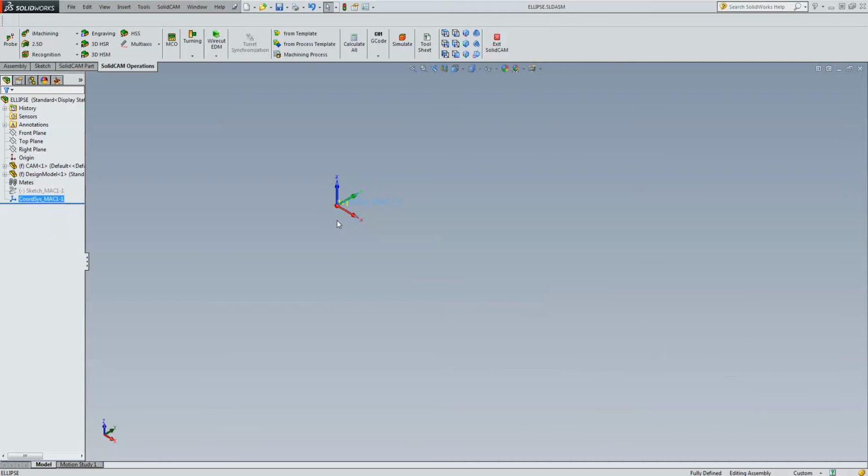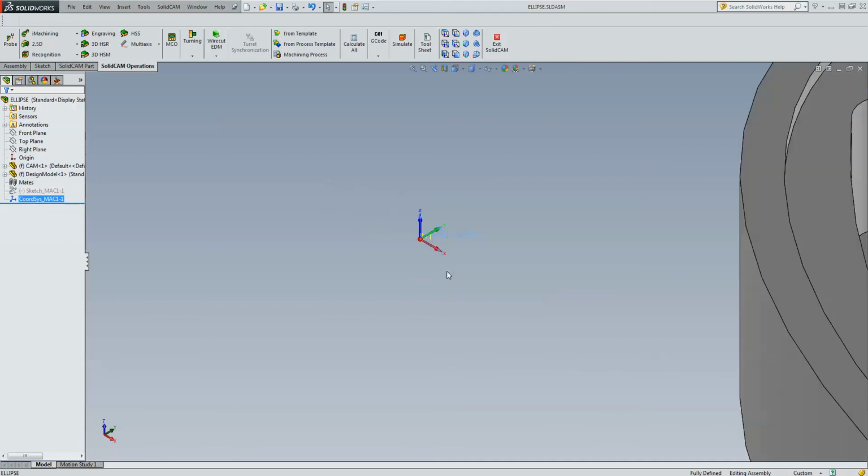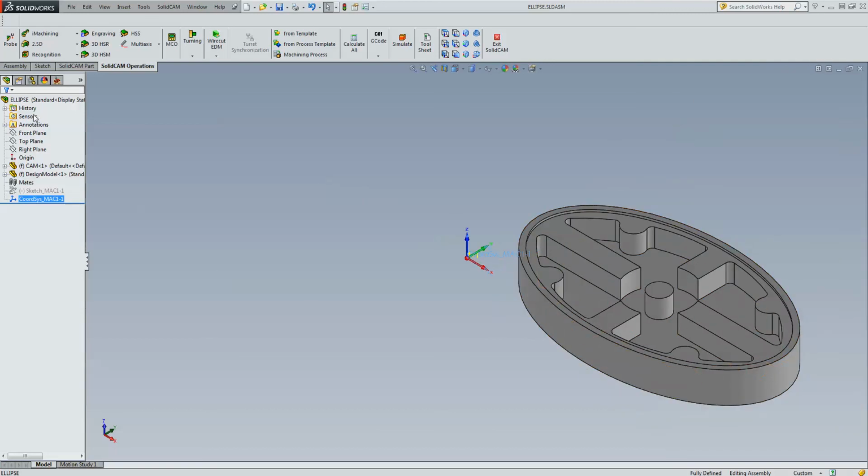This is the actual coordinate system that is created inside SolidWorks again. What you can do with this is also very simple. It also makes it a lot easier to measure from your coordinate system to a different entity on the part itself without having to create a draw point over there to use to measure to.